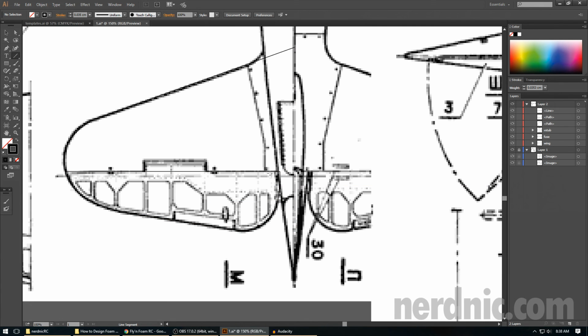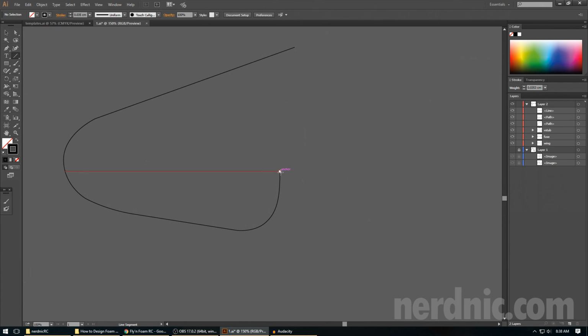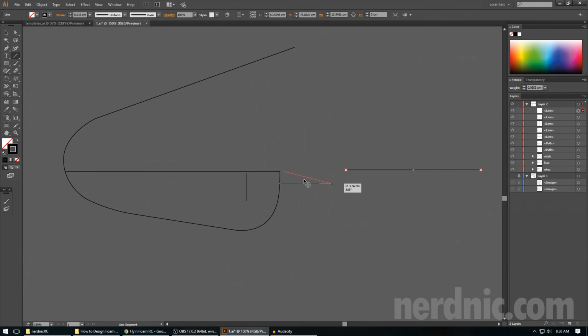The distance here I would highly recommend is making this part as thick as possible. So about an inch is what I would say, if you can do it. If you make this too thin, where the two elevators join, then this part will stress and fatigue and break, and so your control horn will be here pressing this surface, and then the other surface over here will not deflect because this piece gets too weak.